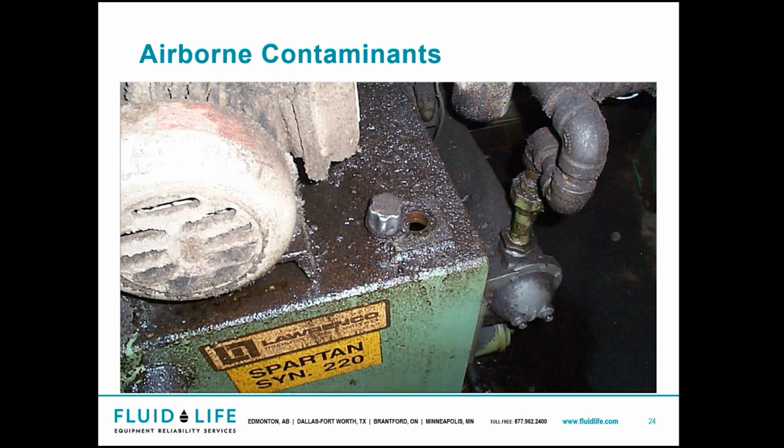My issue with a funnel is we all know what happens with the funnel. A funnel gets used and it's maybe wiped out, and it's used for multiple lubricants and different lubricants and maybe other different fluids, and it's put on a lube cart or a lube truck and then reused again. And again, probably not wiped out. So let's try to make sure that we're doing the proper ways of cleaning it out.